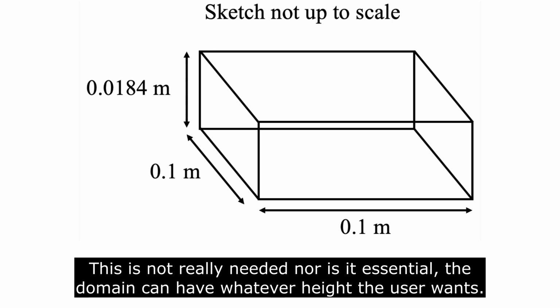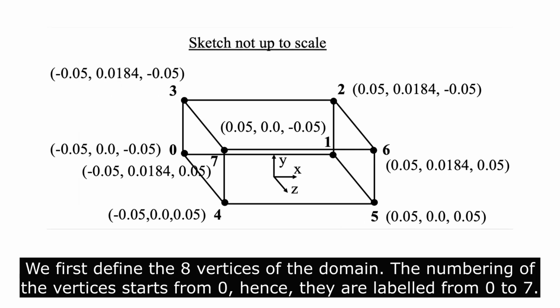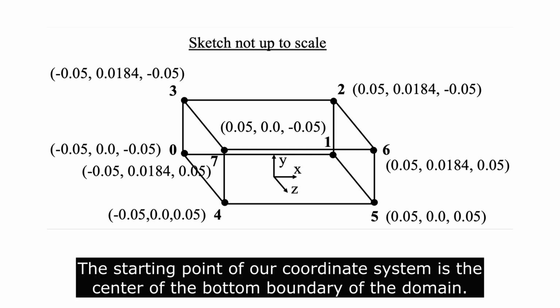This is not really needed, nor is it essential. The domain can have whatever height the user wants. We first define the 8 vertices of the domain. The numbering of the vertices starts from 0, hence they are labeled from 0 to 7. The starting point of our coordinate system is the center of the bottom boundary of the domain.